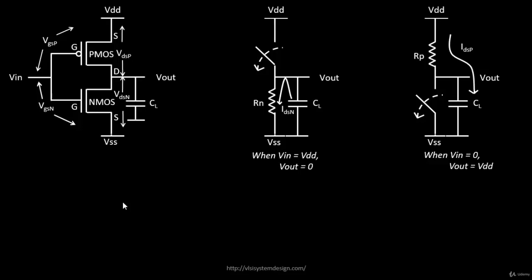When I say voltage transfer characteristics, it's purely a function of voltage. Okay, we have to identify whenever the input voltage rises. For example, take the case of an inverter, this particular gate. Let's say this was not an inverter, it was a NAND gate or a NOR gate. Everything that we do around digital circuits is based on voltages. What is the input voltage you provide and what is the output voltage you get? So it should all be a function of V out and V in, and that's why the CMOS voltage transfer characteristics has come into the picture. Okay, and that's why it becomes very important to do it.